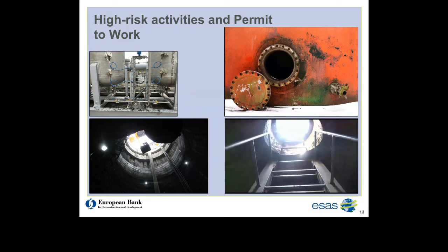One of the key problems is that the project hasn't defined what constitutes a confined space. It's important for workers to clearly understand this. For example, the site has a number of deep excavations. These could be confined spaces, especially considering chlorine is used on site, and chlorine is 2.5 times heavier than air and may settle in a trench.